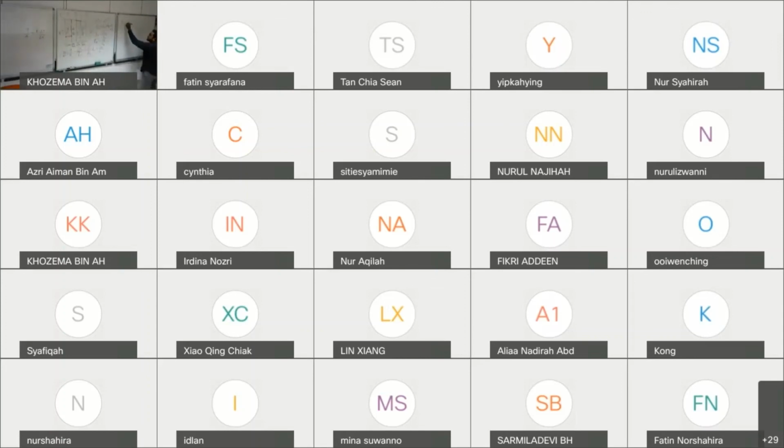So delta T will be equal to T1 minus T2. The question is asking us to find the value of the interface between plaster and brick, which is T2. So based on this, you can see that T2 is equal to T1 minus delta TA. So that is how you will get the value of T2.